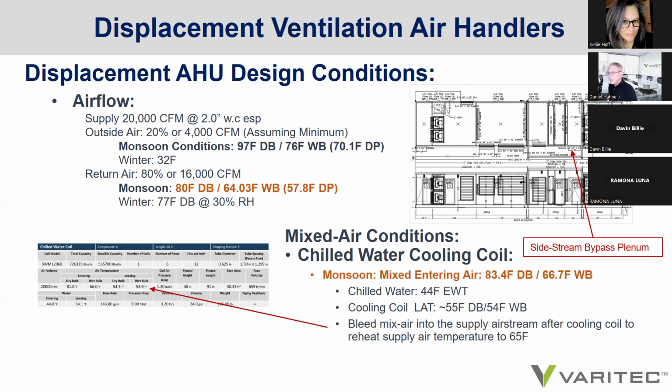You have an air handler with a plenum section attached that spans from the inlet to the outlet of the cooling coil, with a modulating damper at the inlet that is connected to a discharge temperature sensor at the air handler. It modulates the unconditioned mixed air, open and closed, to put it into the supply air stream post coil to provide free reheat of the air. So let's look at that psychrometrically.